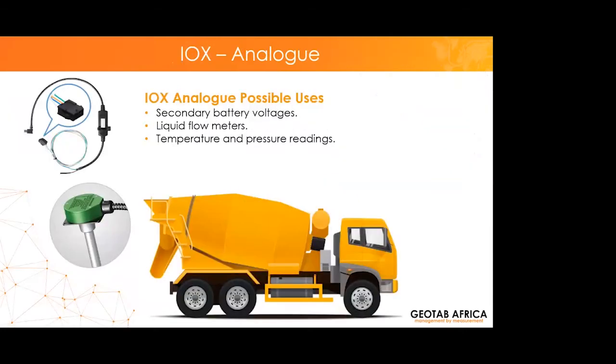IOX Analogue, another IOX expandable. The IOX Analogue measures voltages 0 to 30 volts. Thus, from sensors, we can read the voltages as they change, and where my Geotab will convert those voltages to heights, depending if it's a fuel sensor, it will take those voltages and measure and give you the output of fuel levels. We also have incorporated sensors with the IOX Analogue where we monitor cement drum trucks, whether they're either mixing or offloading.